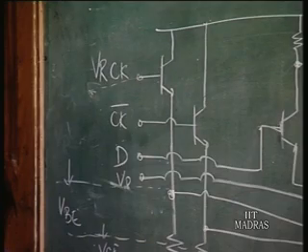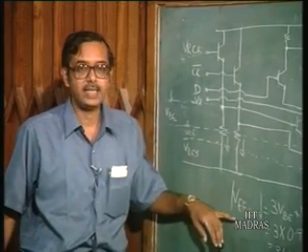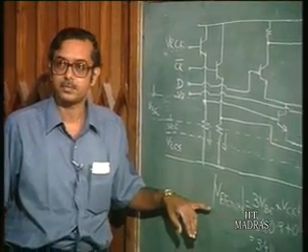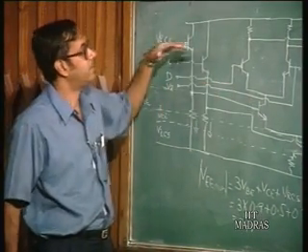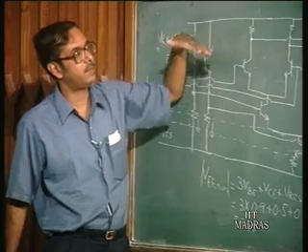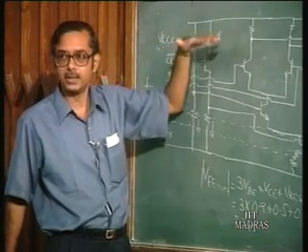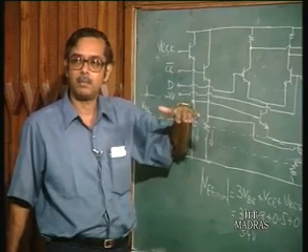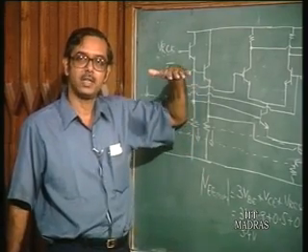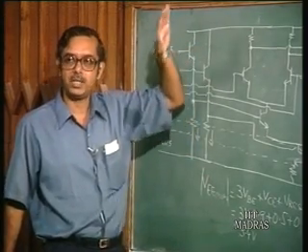Okay. So what is happening? What has happened now? What is the change in the VEE minimum? So basically what we have done is we have increased the input voltage by VBE. All right, it was initially, in the previous circuit, minus VBE to minus VBE minus 500. So we have raised the input voltage by VBE, shifted it up.